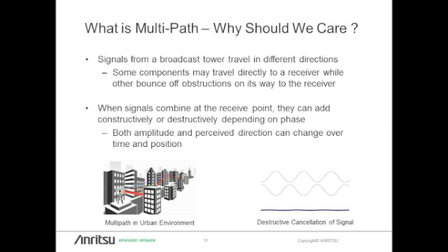And also, in addition to a direction problem in terms of identifying where it's coming from, you have amplitude issues, and that's shown on the bottom right. So in this particular situation, you have two signals. Here I'm just letting them be sine waves, and they're 180 degrees out of phase. So they basically subtract and you come into a null, which is that little bottom line.